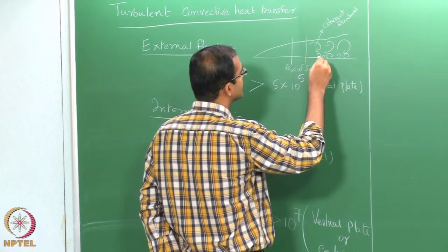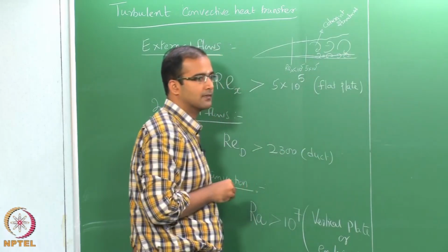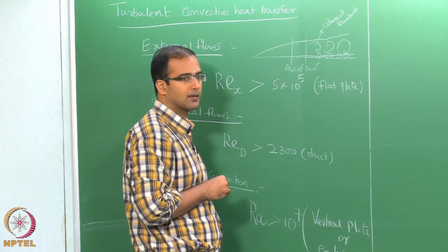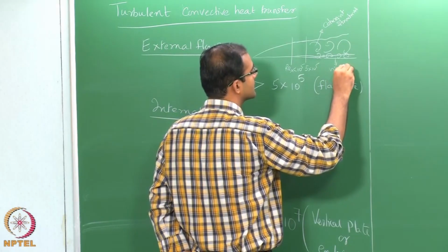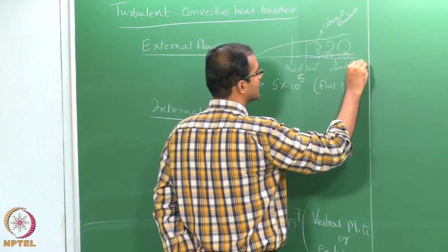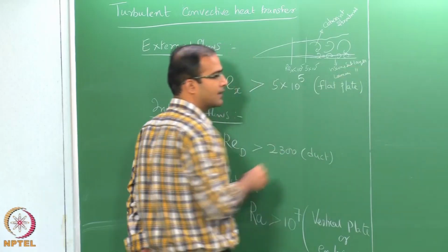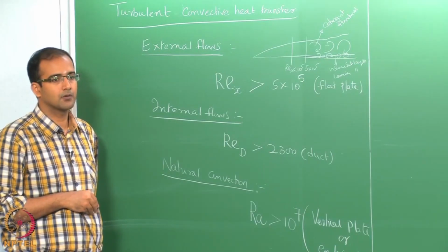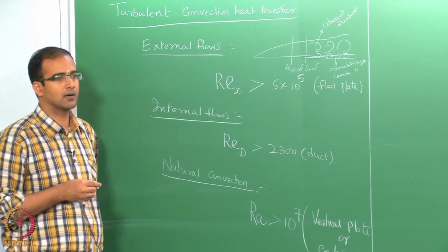So, essentially near the wall you have the effect of viscosity, which is molecular viscosity, which is predominant as compared to the turbulent motion, and therefore this will be referred to as the viscous sublayer or laminar sublayer, okay. Now the action of the wall is to damp the effect of turbulence. Without the confinement, without the wall, you do not have a laminar sublayer, and you only have a range of scales in turbulent flow.